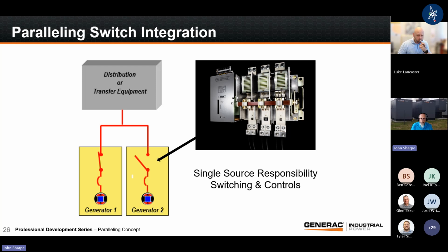You can use a motor operated breaker on the generator itself. So you're again taking from the switchgear that electrically operated breaker and putting it on the unit. Or, and again, that's something I showed you before, I can take a motor starting contactor and have that be the device. It's a very cost-effective solution for getting there. Electrically operated breakers that are small are pretty expensive, relatively speaking. And so maybe going with a contactor, an inexpensive device, makes things a little bit easier to be palatable.